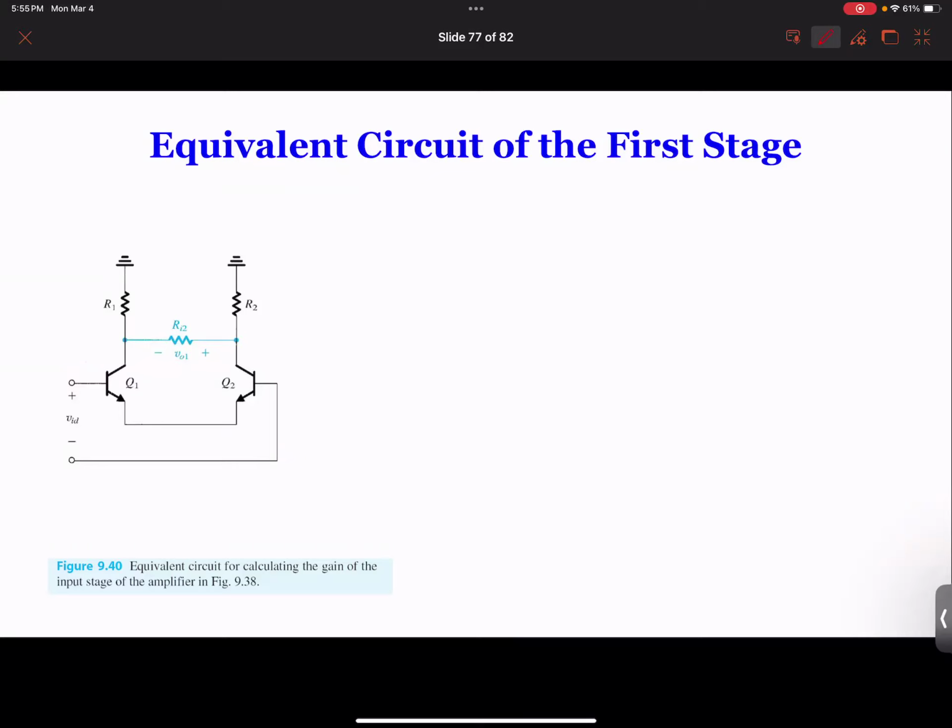So for stage 1, in the book, it will say, okay, by inspection, we can find the gain is going to be the resistance at the collector over the resistance at the emitter. And they study also by looking at the input resistance. So in fact, if you have a doubt at this time, you can start with a pi model. So if that makes your life easier, do that. I'm going to do the pi model.